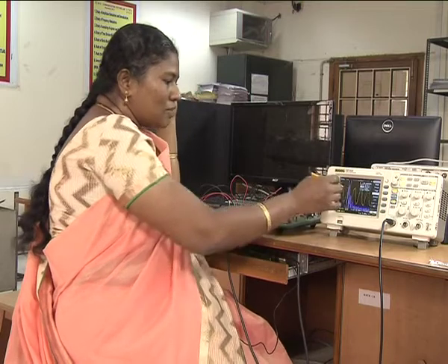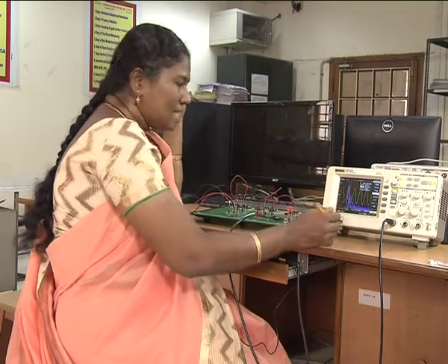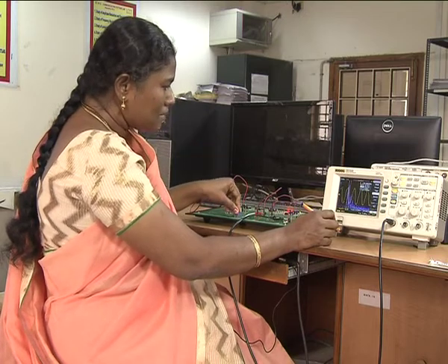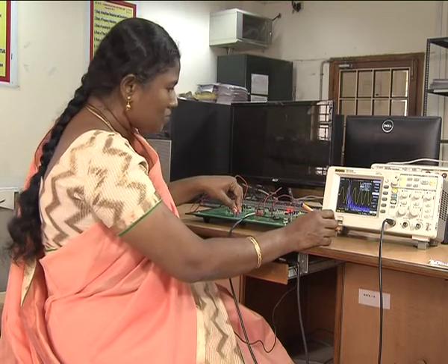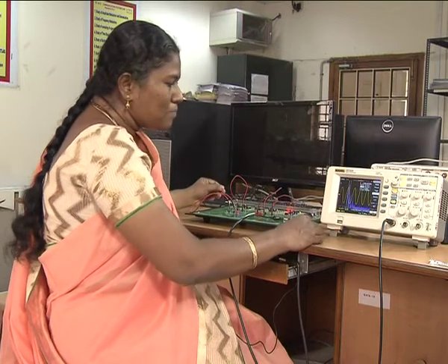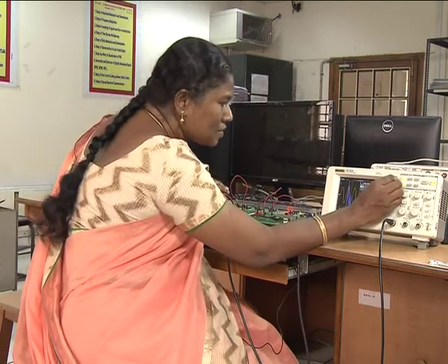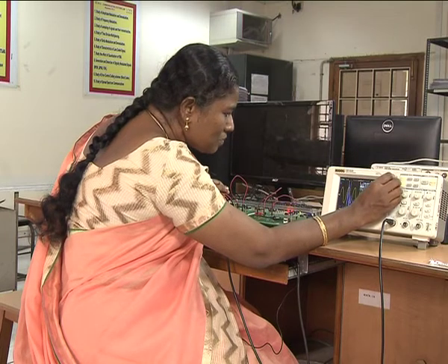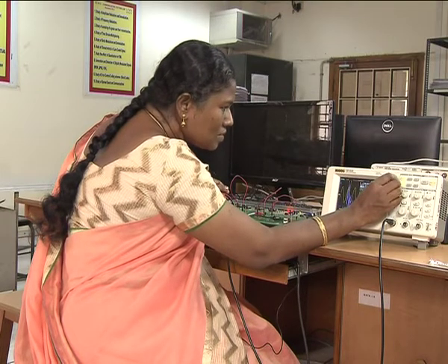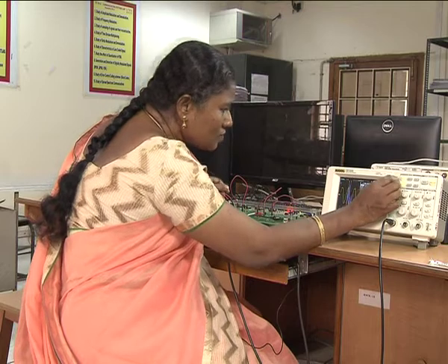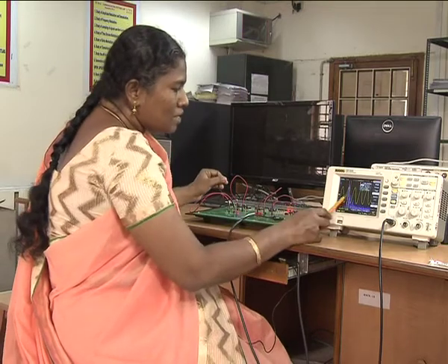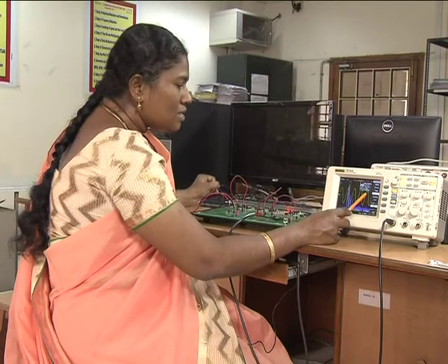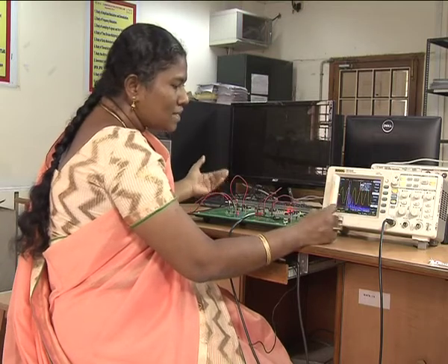You can note down this as one of the observations. For the second case, you can adjust the amplitude of the input signal to any number and repeat the experiment by placing the cursors. Now the cursor is at B. I am placing the cursor at the minimum most point, and then I adjust the cursor for A. After adjusting, I find out the del F. Here 2 del F is 455 kilohertz. This is the second reading for the second waveform.